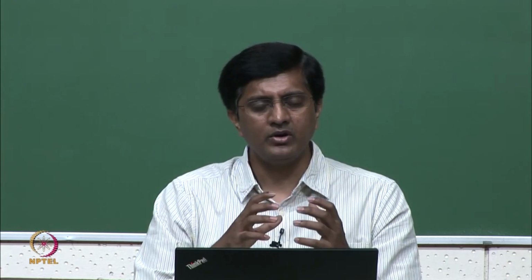So, let us summarize what we have discussed in this lecture. Essentially, we have looked into a few tools of part modeling such as creating splines and using these splines to create solids using the sweep tool, where you need to provide a profile and a path. Lastly, we also looked into the shell command where we can remove the interior material and create cavities of specified thicknesses. So, with this we will conclude this lecture, and in the next lecture we will look at an example where we use some of these features to create a solid.